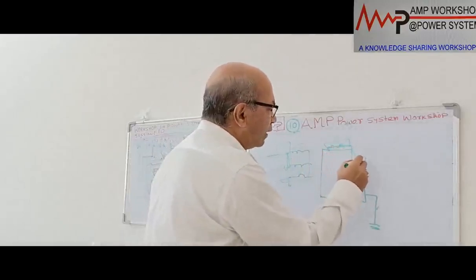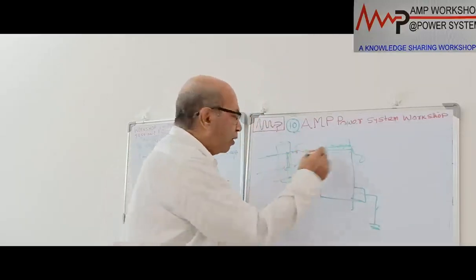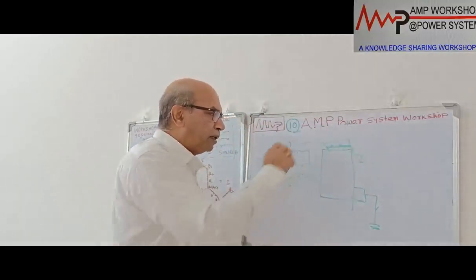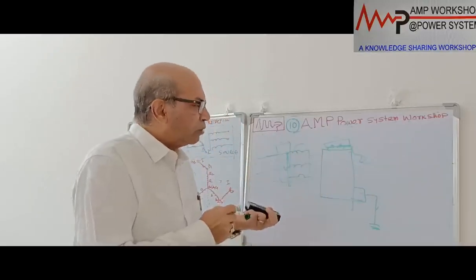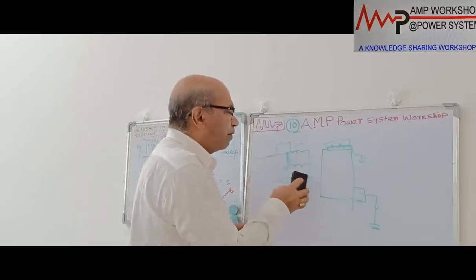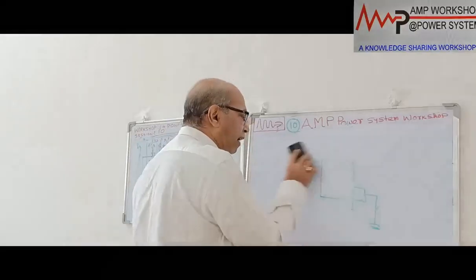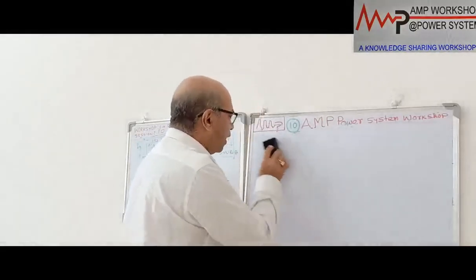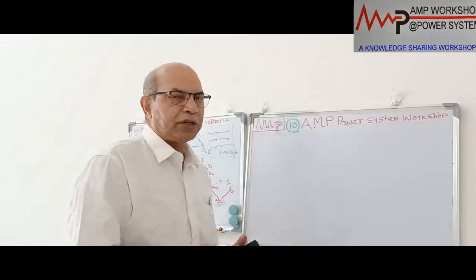If there is an earth fault in the terminal box, in that case also the earth fault current will flow through the local path. So all this will not be protected by these devices. So to protect from this type of fault, as well as a backup for the internal fault, we provide this zigzag transformer with protection devices.